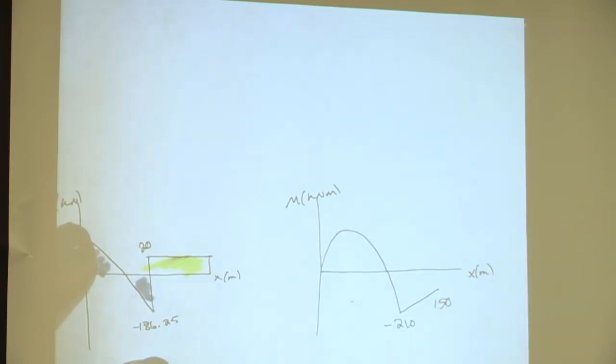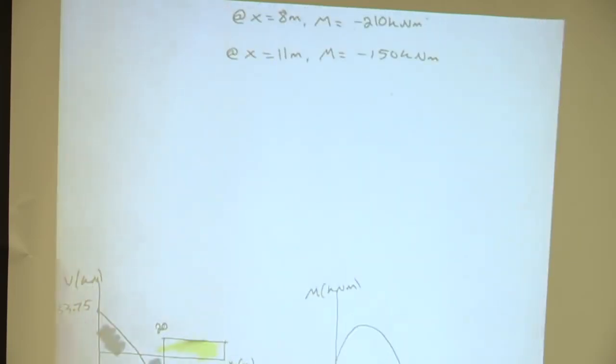It's a straight line, not a curve. Yeah, so you're talking about this part right here? Awesome, so that part's linear. Now negative 150, are we done with this? No. What else do we need to include? The positive moment at C.